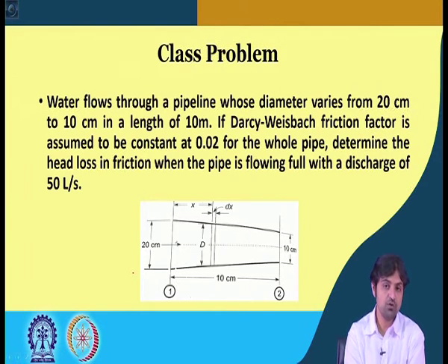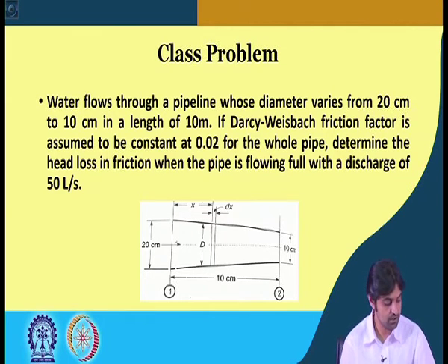In laminar flow, fully developed laminar flow, it was only a function of Reynolds number as 64 by Re. But before going into that, we just solve, if we are given that friction factor f, how are we able to apply these formulas of dhf(x) to find the head loss.